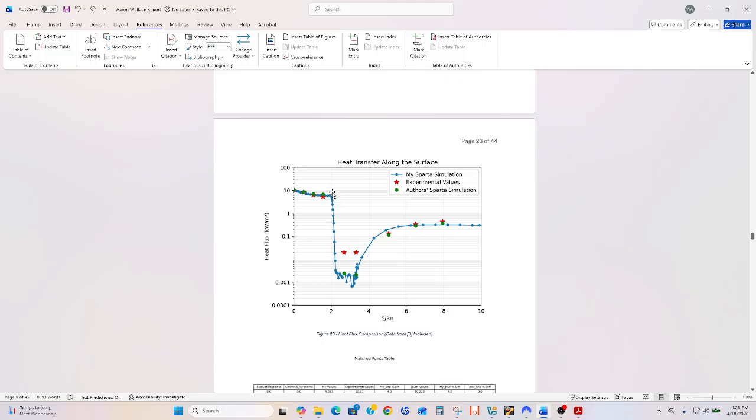The heat flux in the front is way greater than the heat flux everywhere else. So if you were really going to be looking at it, this is where you would be looking on your probe anyway. And I believe that the journal article actually talked about how they used thermocouples on this probe in the wind tunnel testing, and they were saying that it's probably not accurate like it is up in the front of the probe because of the variations that were going on in the, I guess, downstream end.